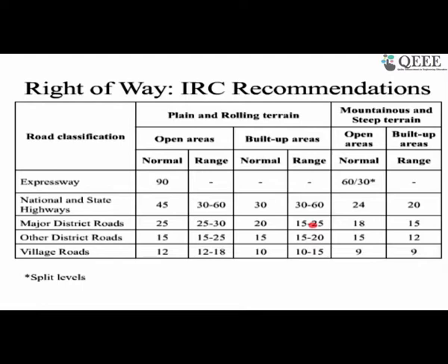In the urban setup, another thing is that the road is not going to be elevated, or you won't see an embankment in the urban setup. So you are looking at the pavement or carriageway width, some distance for the side clearance from the curb side, about 0.15 meter or so on either side, and then a footpath, which depending on the standard they are going to follow can be 1.5 meter to 2 meter.